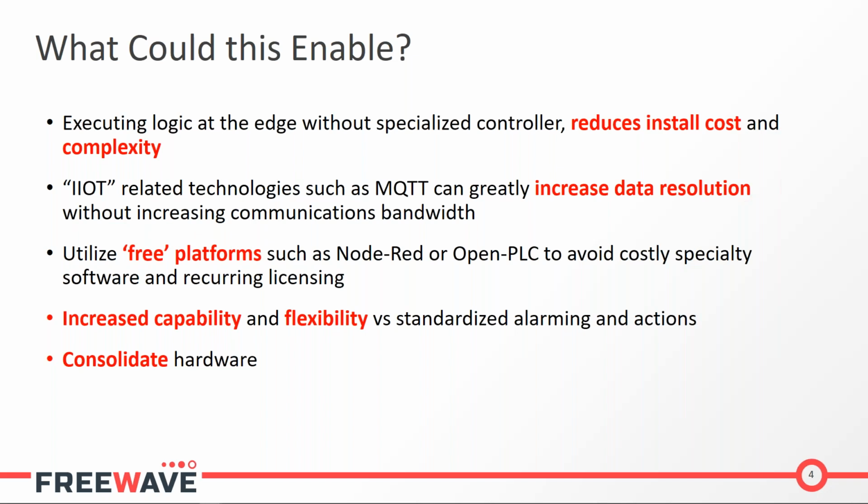You can program it to do something the way that you want it to do versus canned actions or canned logic that may be in some specialized software and devices. Similar to a PLC, however, with a PLC or an RTU or any other controller, if you're trying to get that data back to your office or to some remote system, or if you have several endpoints that you want to have a centralized control capability on, you're also going to have some communications hardware in with them as well.